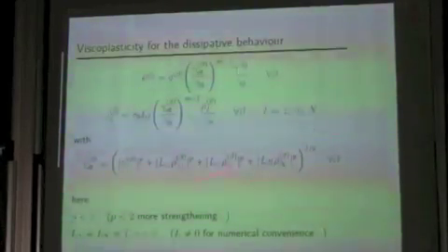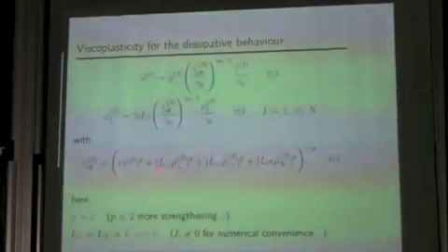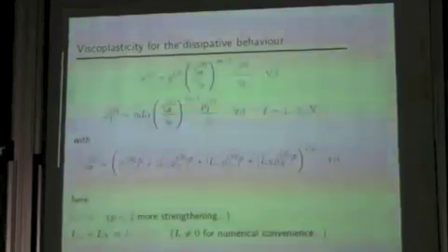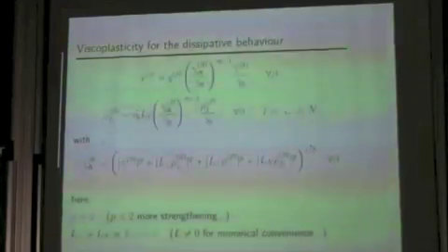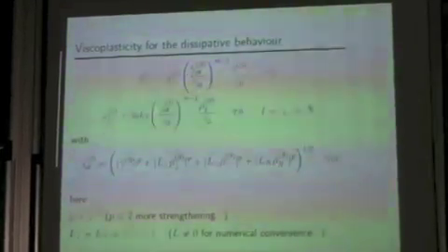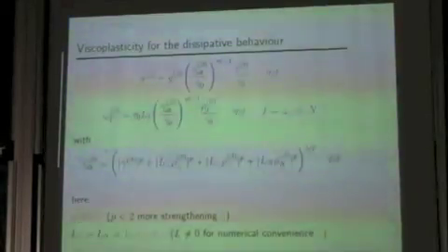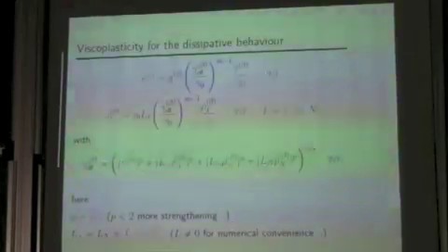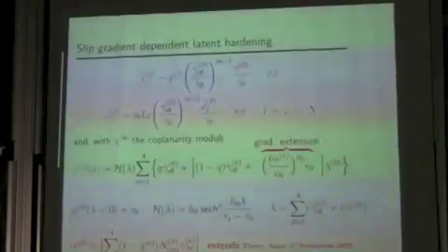After some tests, finally here we'll use the Euclidean norm, and for all the dissipative length scales we'll use the same number, which should be about 0 to avoid strengthening, but we'll take it as small as possible. We cannot take it really 0, because otherwise it's really hard to have convergence in the finite element simulation of this problem with gradient plasticity.